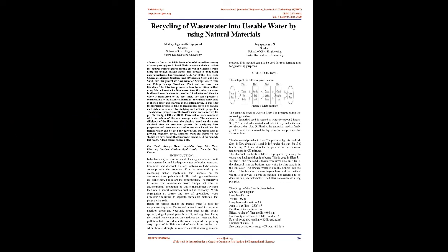For this project we have collected sewage water from our college sewage treatment plant and we have done filtration. The filtration process is done by the aeration method using a fish tank motor for 20 minutes. After filtration, the water is allowed to settle down for another 20 minutes and then the water is transferred to the next filter. The same process is continued up to the last filter. In the last filter there is fine sand in the top layer and charcoal in the bottom layer. In this filter the filtration process is done by gravitational force.